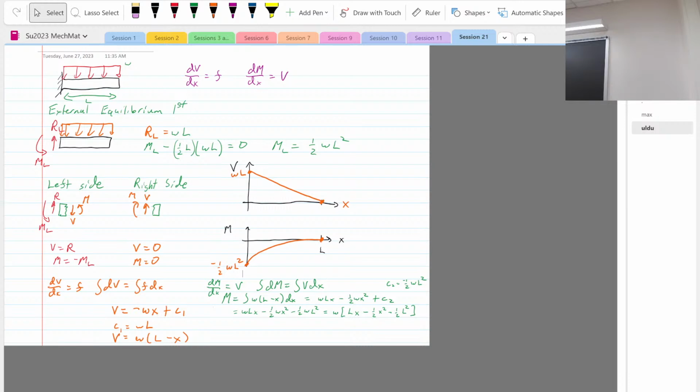So what we're getting at here, right, is that if you have a point on the neutral axis, what is the y? So if you have bending about the z, so let's say we have a bending moment, which is what Py is doing. The effective length of action is a, so you have this Py a, right? And that axis is z. That's what it's bending about. For that beam, A is on the neutral axis.